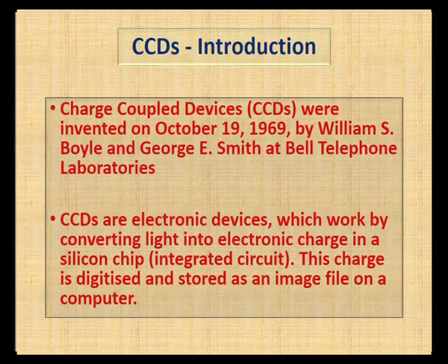The charge coupled device is a device which converts light into electronic charge. The device operates as the electronic charge is formed with the application of photons. When the photon is applied to the cathode terminal of a semiconductor device, the electrons are ejected from the surface, which produces charge packets. We will discuss further the different steps of how these charges flow from one cell to another.